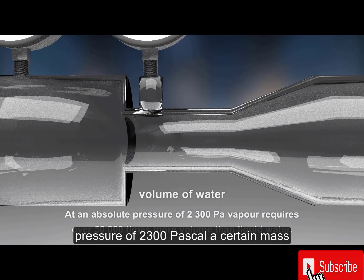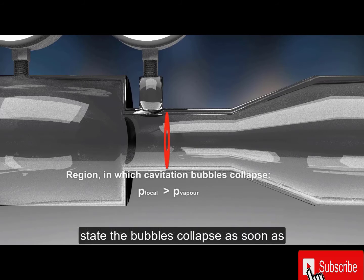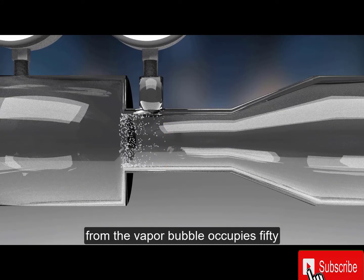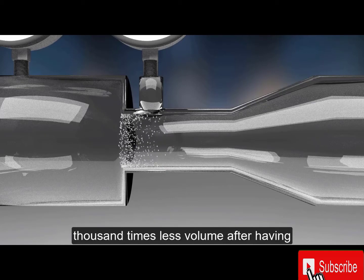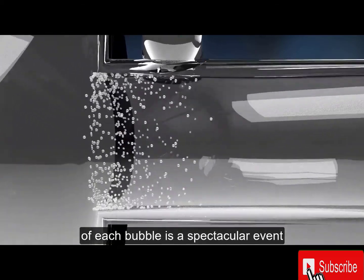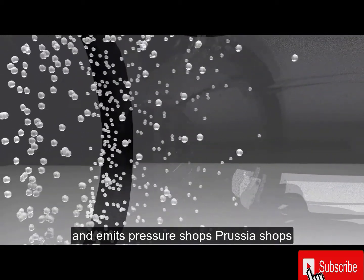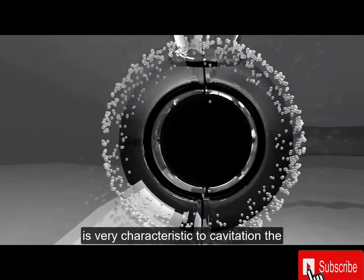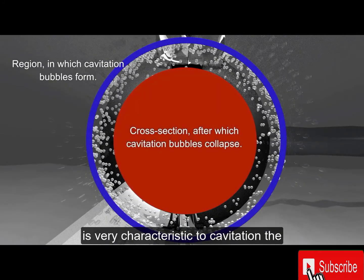At a pressure of 2,300 Pascal, a certain mass of water vapor requires over 50,000 times more volume than in its liquid state. The bubbles collapse as soon as they reach a region with a pressure above the vapor pressure. Because water from the vapor bubble occupies 50,000 times less volume after having condensed to its liquid state, the collapse of each bubble is a spectacular event and emits pressure shocks. Pressure shocks from many collapses result in an audible noise very characteristic of cavitation.